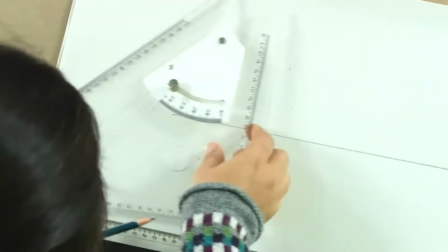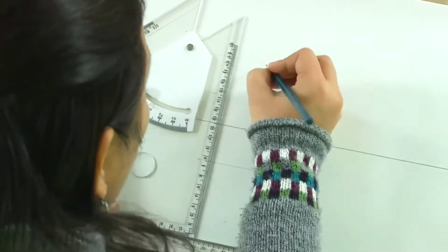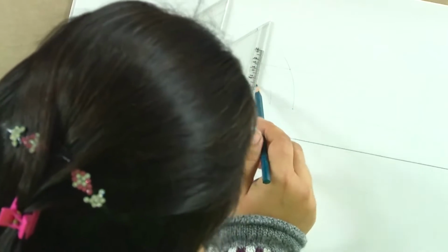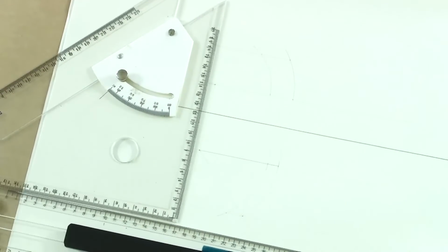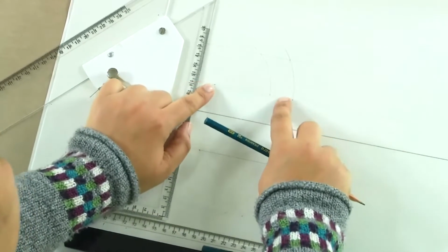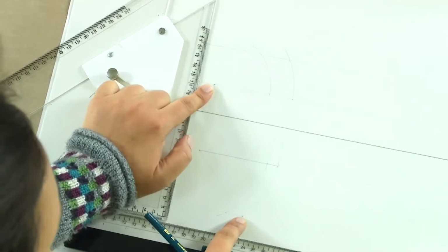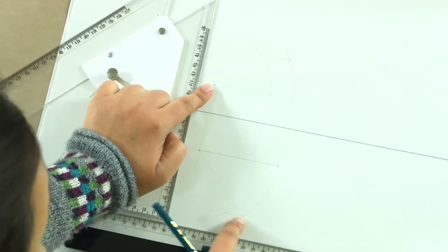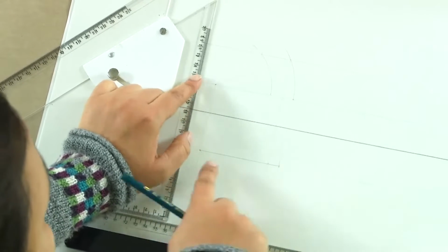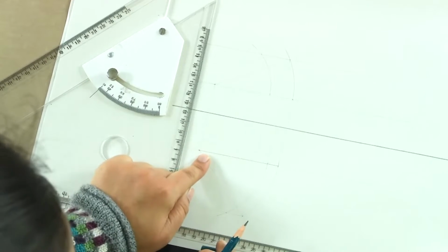So I am doing simultaneous drawing, but if you see, this is the point and this is the point here, which ideally should match in a straight line, because now here what we have done, we have taken the projection of this line which was inclined at HP to a locus, to a line, a path, which is obtained by inclining that same line at 45 degree to VP.